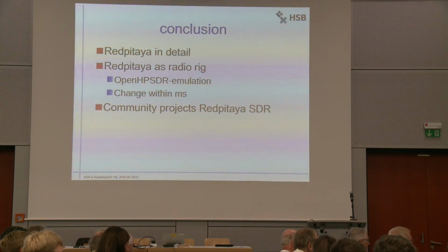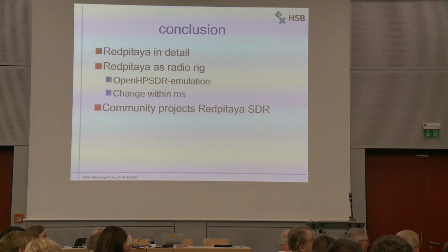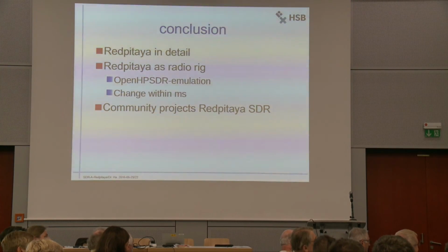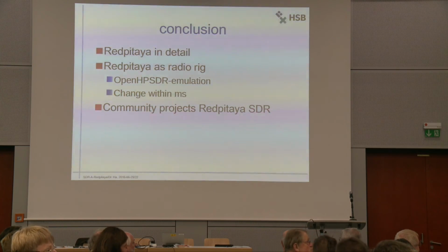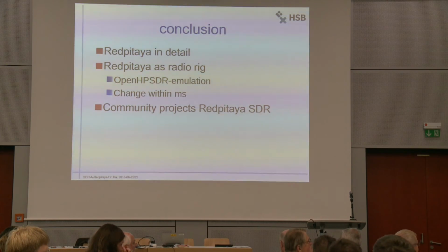If you go to our wiki page, there is an example. You have to replace 2 resistors, and you can bring in the external clock. And there are companies that did that. I think it was for spectrometry or something. But for that, you have to remove the heat sink. Yes, it's true. But it's easy. You will not damage anything.